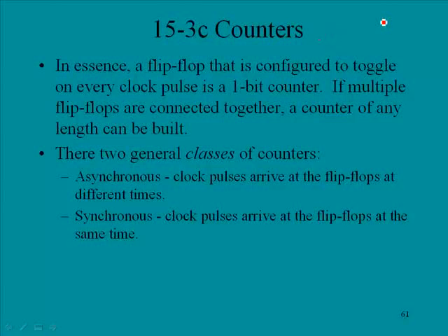They are the asynchronous variety, where clock pulses arrive at the flip-flops at different times, and then there are synchronous counters, where the clock pulses arrive at the flip-flops at the same time, meaning that the clock pulse is simultaneously fed into all of the flip-flops at the same instant.